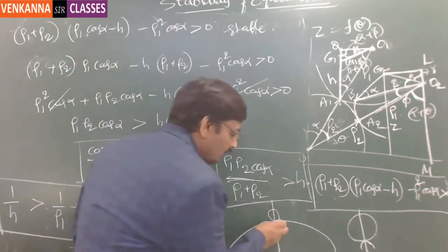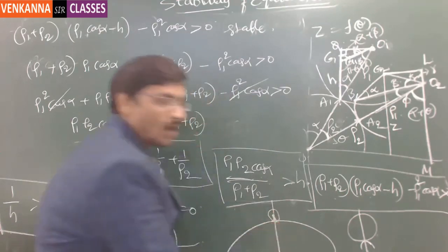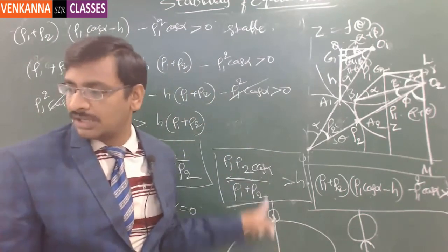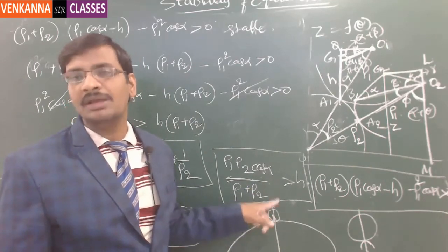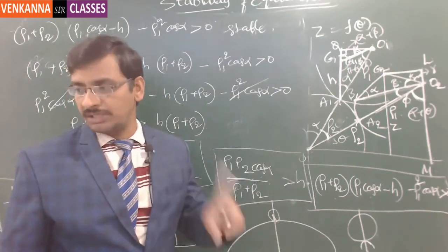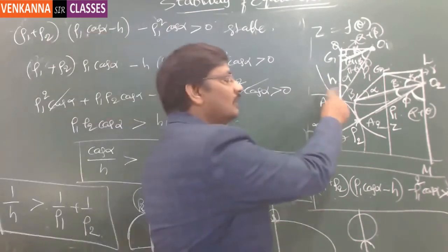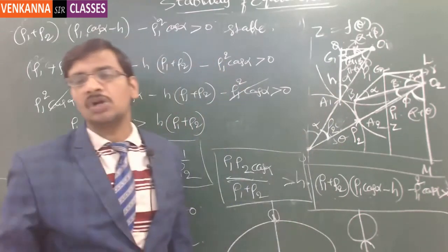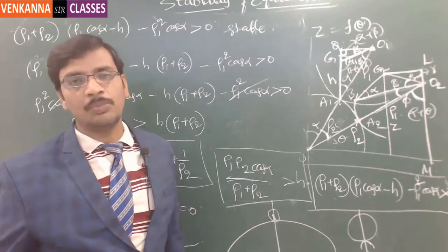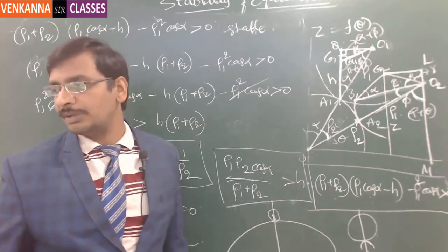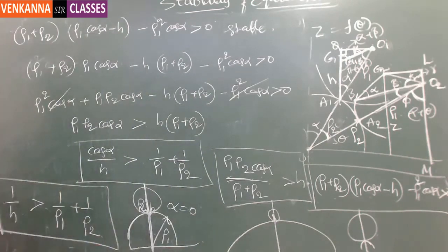And if you notice, from the point of contact to this particular point, this is exactly on top. That means on the same straight line, exactly. So the point of contact and the center of gravity of the top body have to be on the same vertical line. This is the rule. Why? Because even if it shifts a little bit, it automatically goes out of equilibrium. Then there is no point in calculating the stability of equilibrium. I hope you got it. Got it?